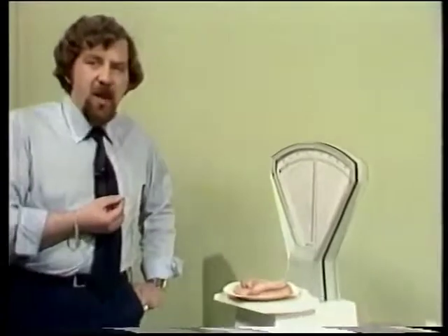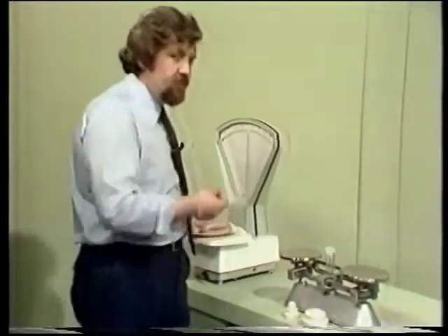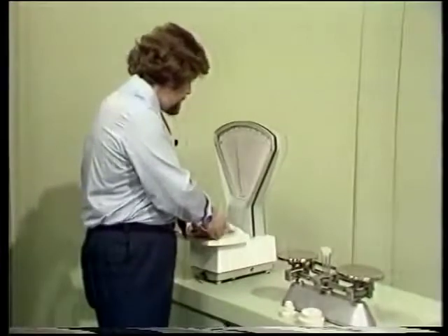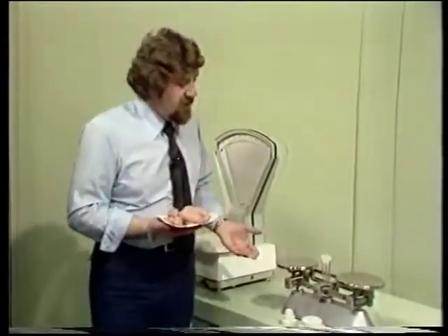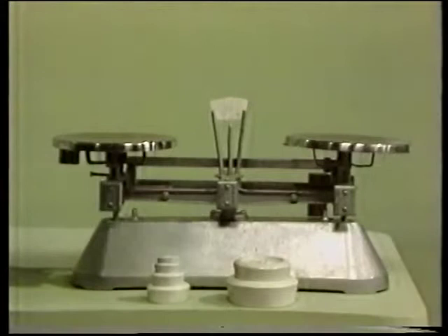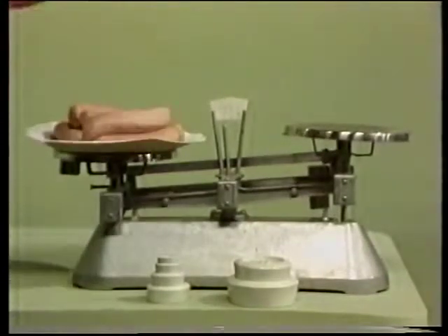My reason for choosing the weighing machine example is that there's a close analogy between analog to digital conversion and weighing with the old balance type scales like these. Let me show you. With these scales, what I do is to compare an unknown weight, my sausages, with a set of known weights, just like the analog to digital converter. In the converter, we compare the analog input with a known digitally generated voltage by means of a device called a comparator. But with the scales, I do the comparison.